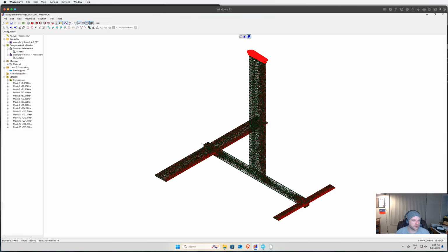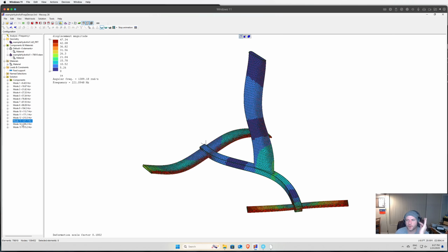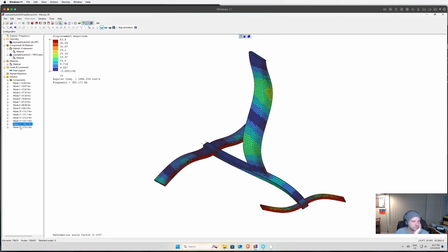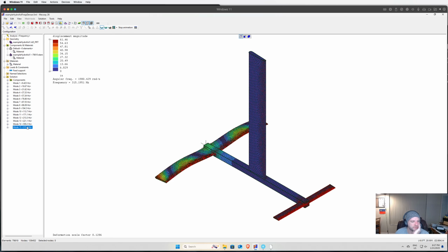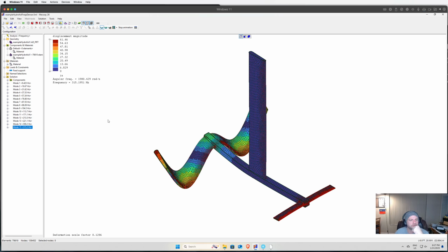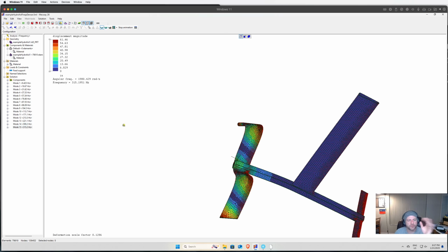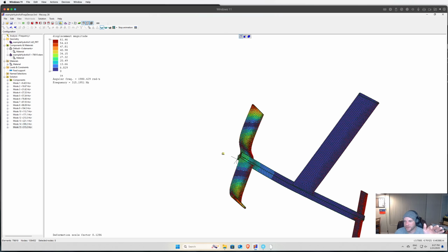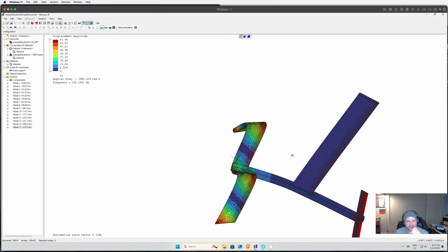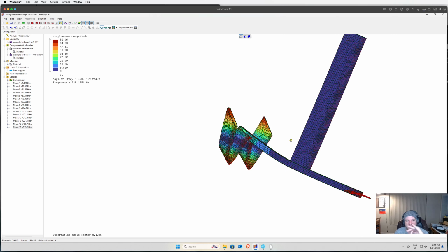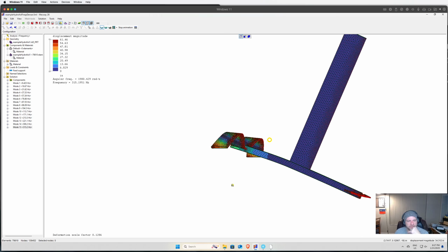But when you look at the TET mesh model, similar mode, you get down to the mode 14, 15, these higher mode shapes. Yeah, it's always interesting to see it dance. Maybe I don't know if I have the results saved with that 16th mode, but you do start seeing this more torsional effect in the higher modes. And I think that's more where you get the classical aeroelastic effects of these things interacting with the fluid flow. Or maybe this is the twisting effect.